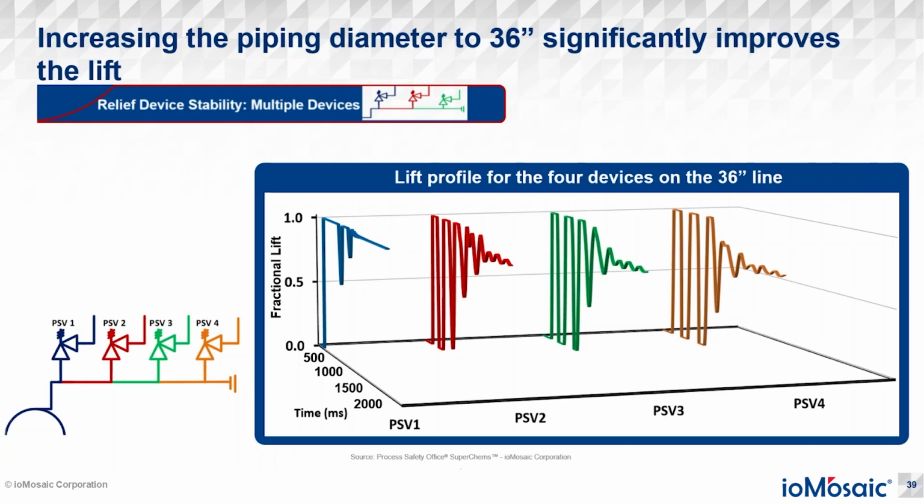We can see here the blue pops right open. The red has again a bit of chattering, same with the green valve and the orange valve, and then they pop open, but they basically calm down after that period of, let's say, 500 milliseconds, 1,000 milliseconds.